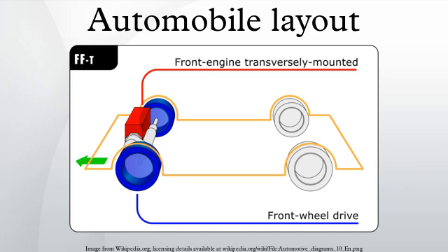Disadvantages. Under heavy acceleration, oversteer and fishtailing may occur as the rear wheels break free and spin. The corrective action is to let off the throttle. On snow, ice and sand, rear-wheel drive loses its traction advantage to front or all-wheel drive vehicles, which have greater weight on the driven wheels.